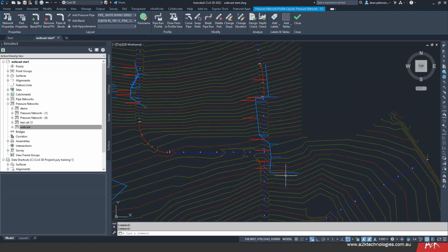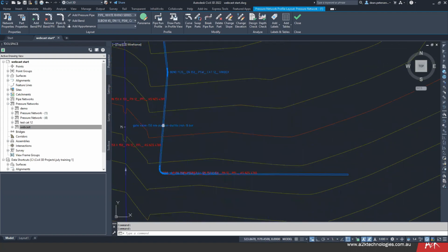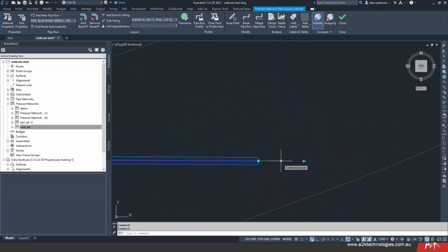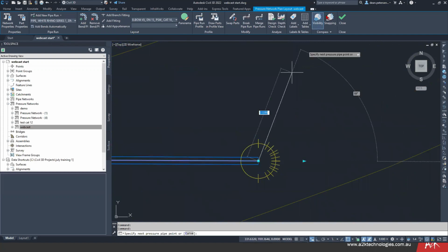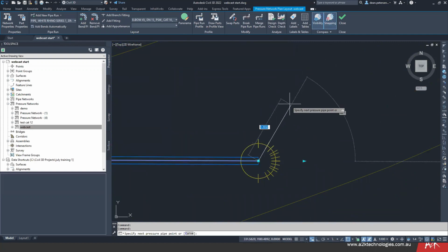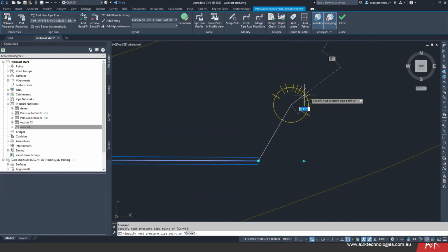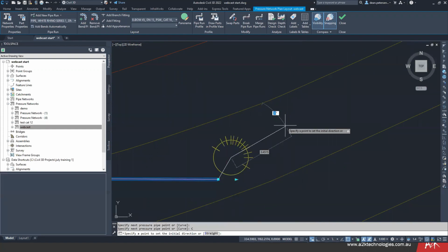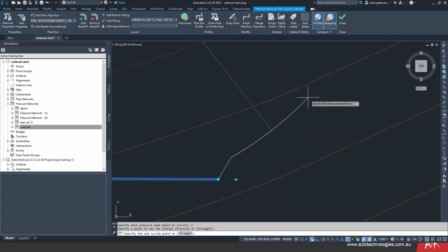Oh, these do have bends. Now, if you want to continue drawing, you can pick one of these. There's the little plus on the end to go continue layout. You can put a new pipe, turn the snapping back on, that angle. And if I wanted a bent pipe, so we can go curve, and you can give it an initial direction. I want the initial direction in that way, so it's going to put in a bend of that much.